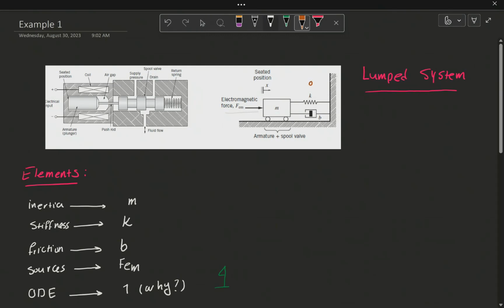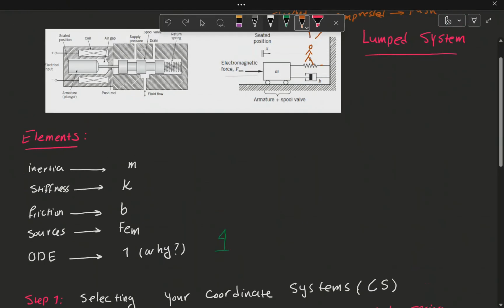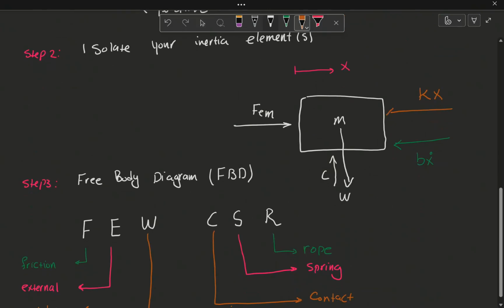spring force is to assume yourself as the spring. So if you are the spring and the box moves toward you to the right, are you going to be compressed or stretched? Okay. Definitely when the box goes towards you, you're going to be squeezed between the box and the wall. So you're going to be compressed. When you are compressed and you want to get rid of that compression, you are going to push back. So if you push back, you're going to force the spring in this direction. You're going to push it back in these two directions. And that's exactly what's happening to that spring.